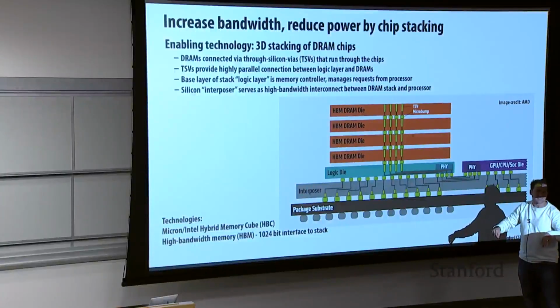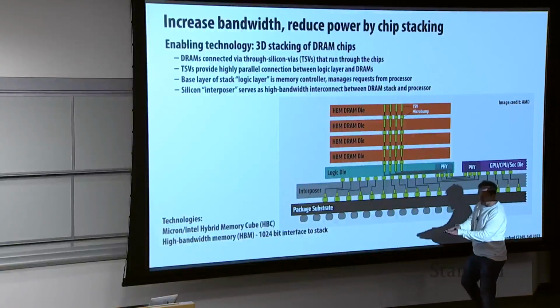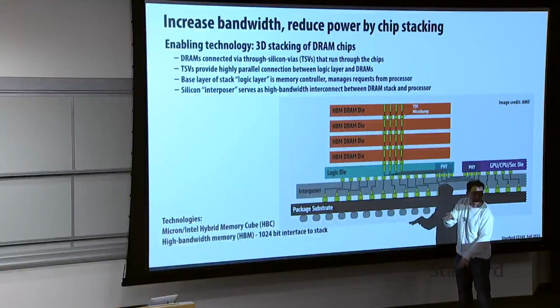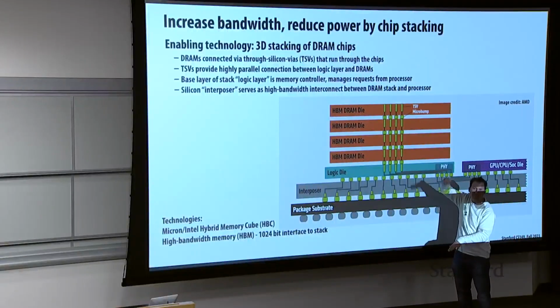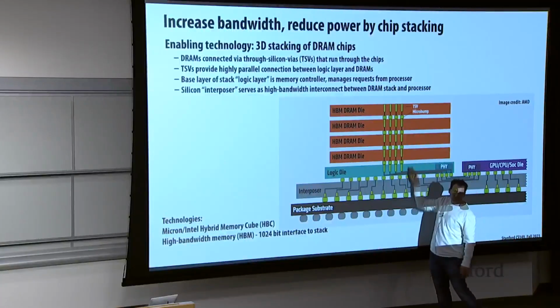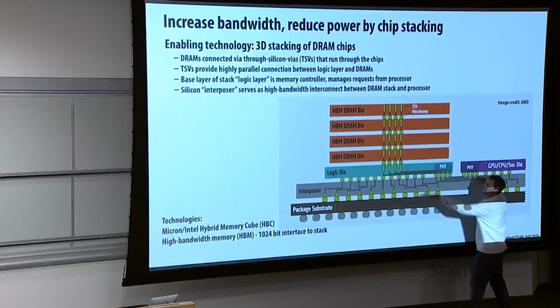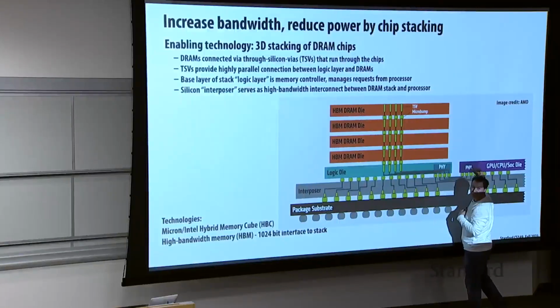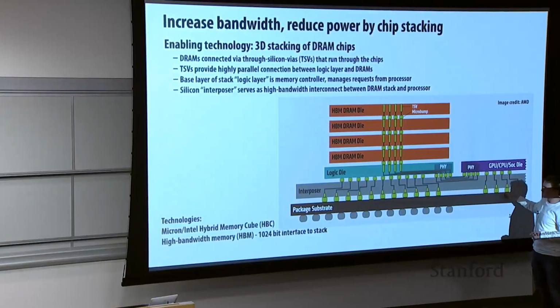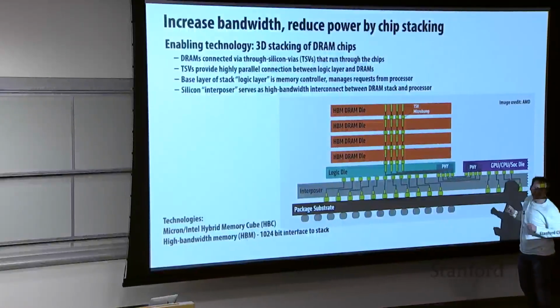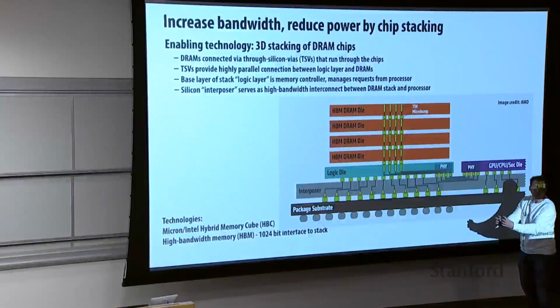So you get an area amount of space and not one edge of the chip amount of space. So you can run a lot more wires right off the bottom of the chip, from everywhere in that array. And those wires have to run through the DRAM chips below it. So there are these vertical wires that then go right into a piece of silicon right over to the GPU. So if you bought one of these things, this is all in the same package. What I mean by that is it'll look like one chip.